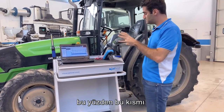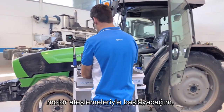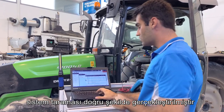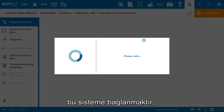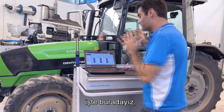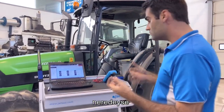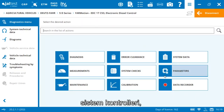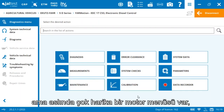So I'm going to keep this part for a couple of minutes later, and I'm going to start with the engine. Ignition is on, system scan has been correctly performed, and the next step is to connect in this system. Here we are. We've got a very nice diagnosis menu. Almost 9 different types of functions: diagnosis, errors, system data, measurements, system checks, parameters, maintenance, calibration. It is not a big tractor, but actually has a very great engine menu.